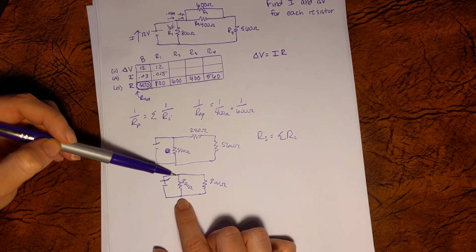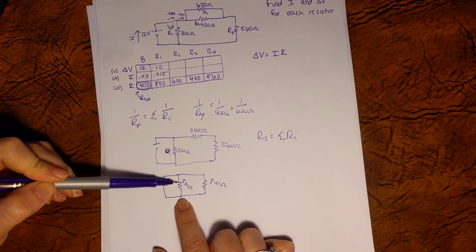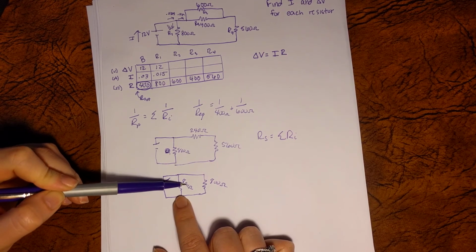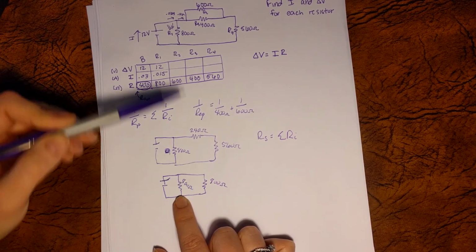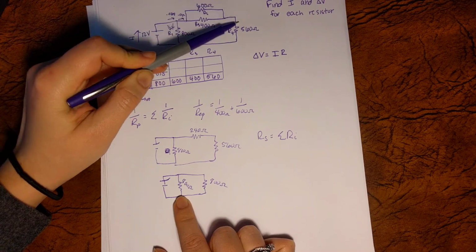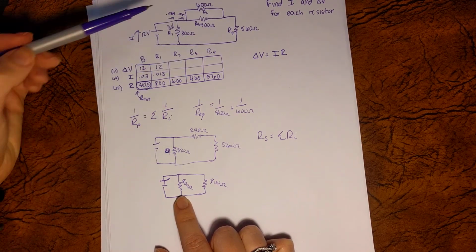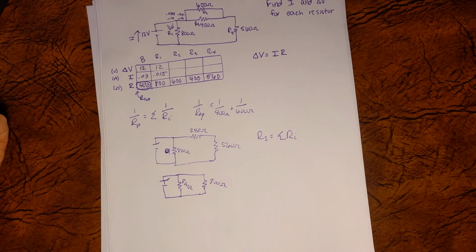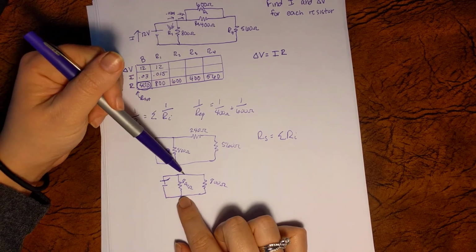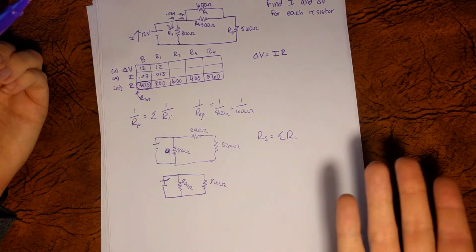Entering in, we have 0.03 amps. Then we have 0.015 going down to the 800 ohms. That means this equivalent resistance, the resistance of all these added together, is also 800 ohms. So it has to have the same current being split. That's why the same current goes through that part of the circuit. So that's why that is.